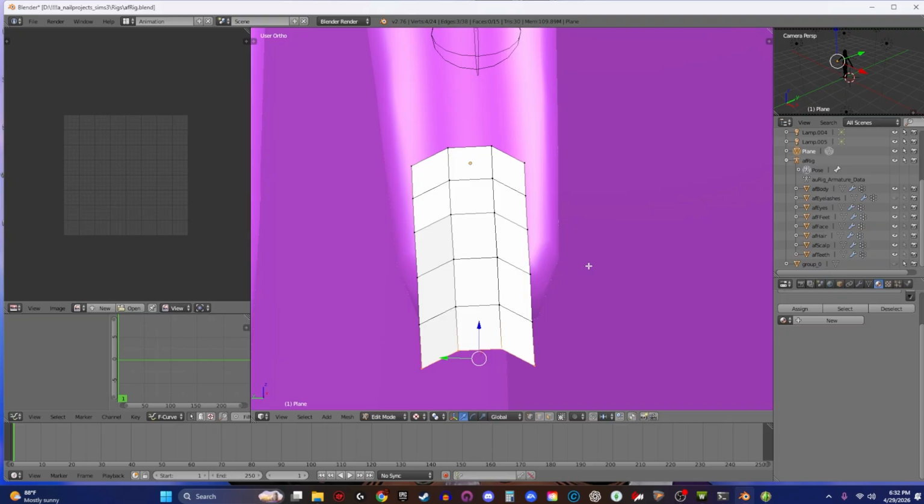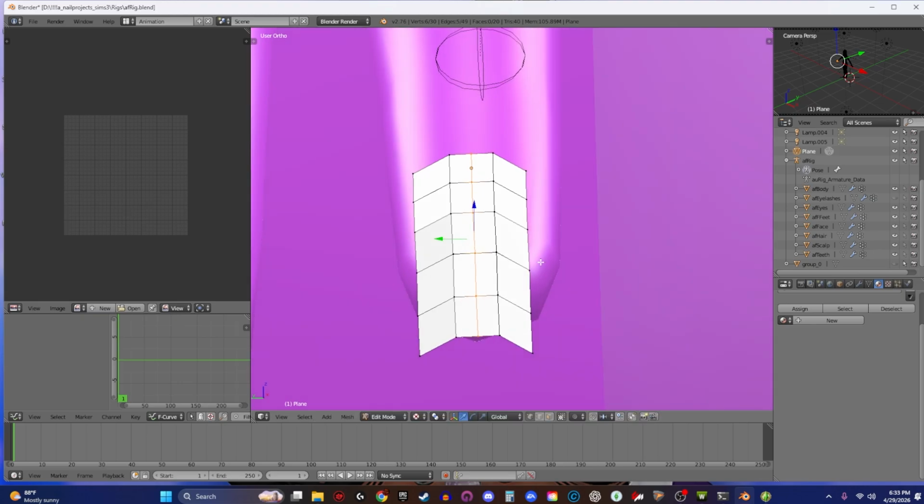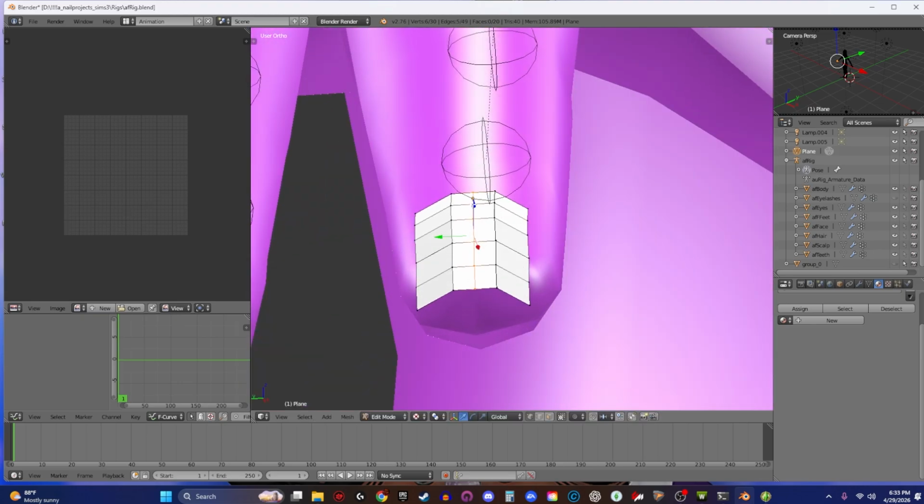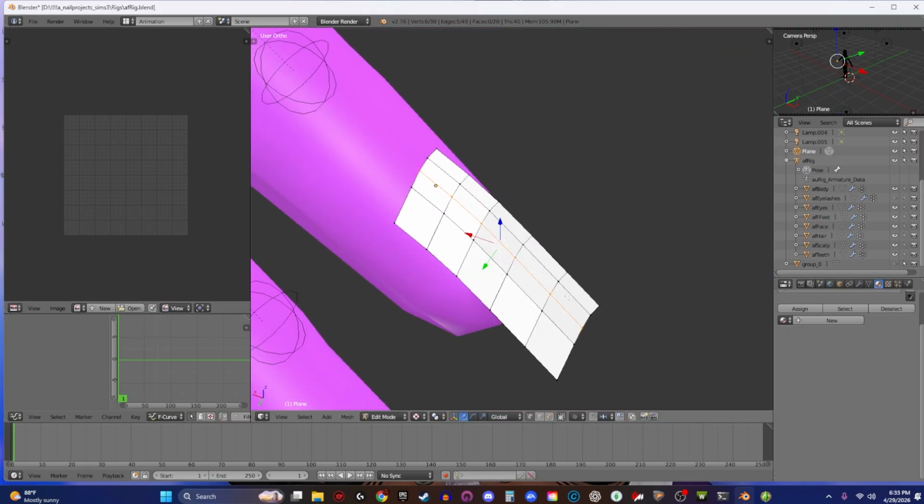So I'm gonna hold Control and then click R. That's gonna bring in this line, this reddish pink line, and then we're gonna put it in the middle of this plane. And then it's gonna bring in the orange line. It's gonna be moving because you have to confirm it. So you're gonna find the spot and hit confirm. This splits it up. And we just want to edit that curve.